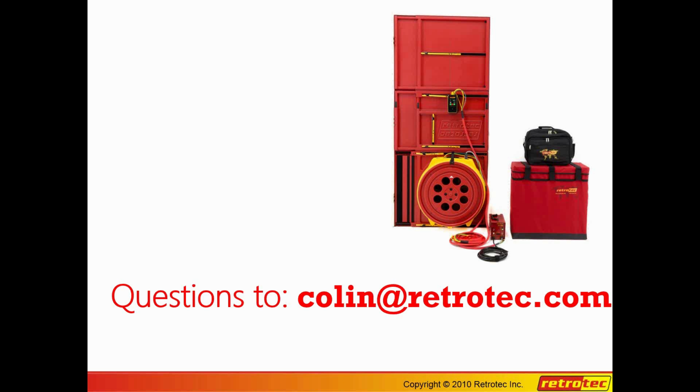So someone was asking, can we install it on the raised floor? I'm not sure if you're asking, can we install the PRVs on the raised floor? I wouldn't suggest that. There probably is not enough pressure in order to open the PRV. The PRVs usually open at around 50 to 80 pascals, and the column pressure of the agent for inerts is around 1 or 2 pascals.